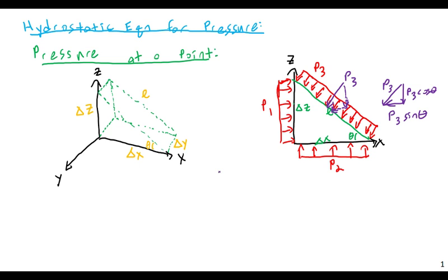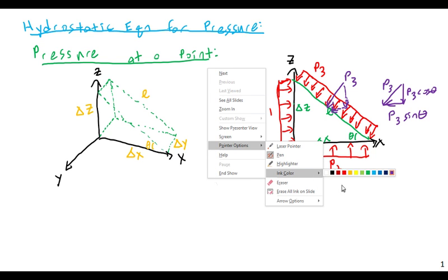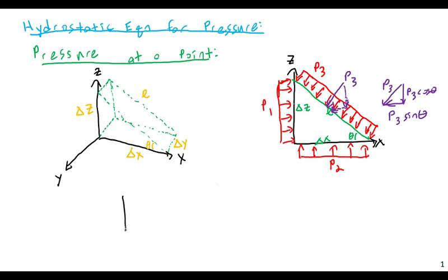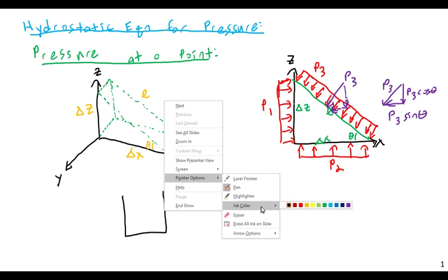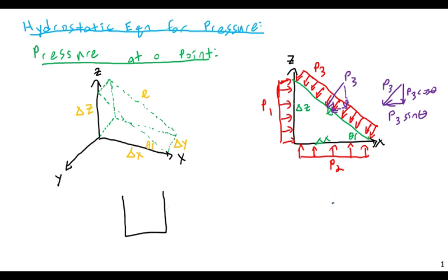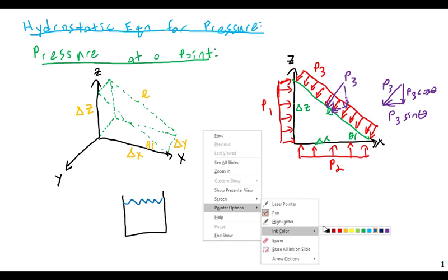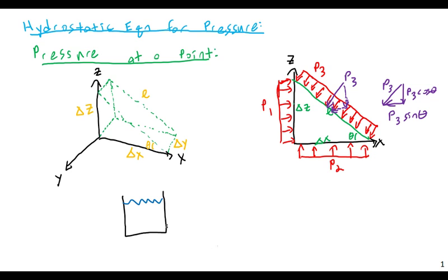So again, this is a fluid prism that's sliced at a certain plane. Because a fluid, if you remember, can be sliced at any plane, and the reason it can be sliced at any plane is because there is no shear on it. We defined that earlier, that a fluid, by definition, will not be able to experience any kind of shear force, and so it will not have shear on any plane.